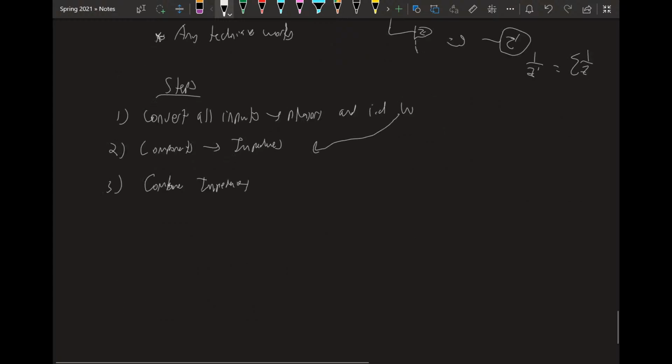And then step 4, you use whatever technique you want to solve for what the question is asking for. Node, mesh current, complex algebra, phasors, use whatever. Solve for it and then convert it back to cosine form for your final answer, because that's typically what professors want. And so here I do have an example.